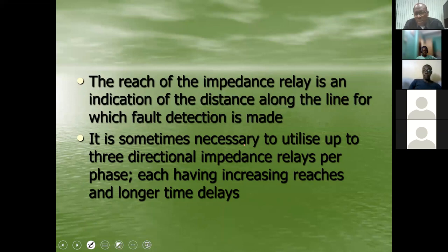for you to cover a three-phase line, and if you were going to look at each phase, then you'll have to have a relay per phase. So you'll basically end up with 6 on each line if you're going to monitor all 3 lines. Good? With your static relay, you have 1 relay, and you'll get the input from all 3 phases.